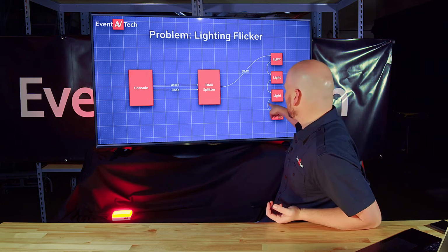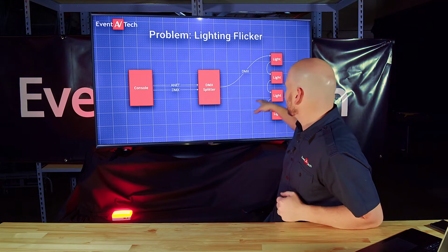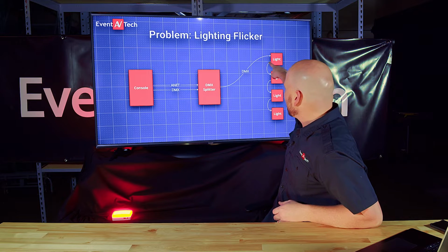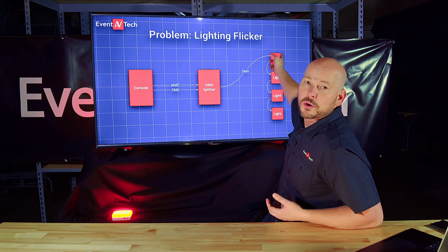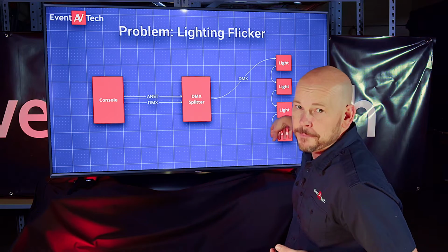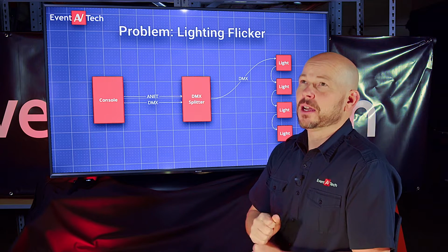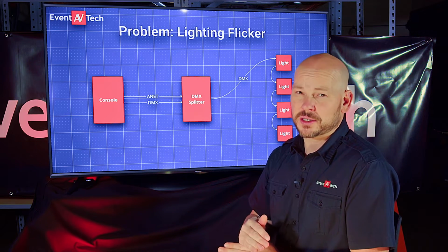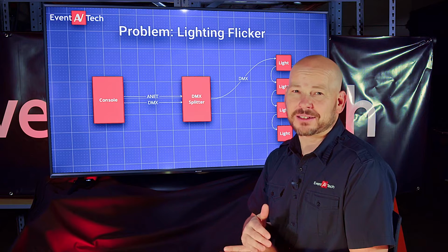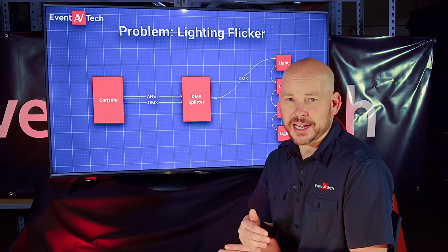So that might be another thing that I'm going to check. I'm going to make sure that nobody that set up that lighting used the wrong type of cable, because if I've got a microphone cable right here, I'm going to get rid of it, throw a DMX cable in, and hopefully that's going to solve my problem as well. What the terminator does is it reestablishes the ohm rating at 120 ohms, which is what you need for lighting.